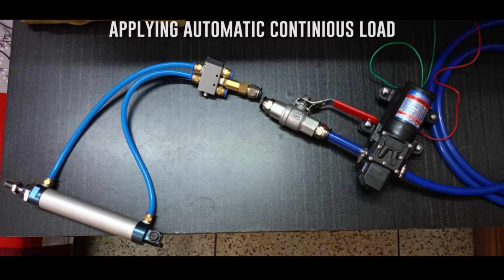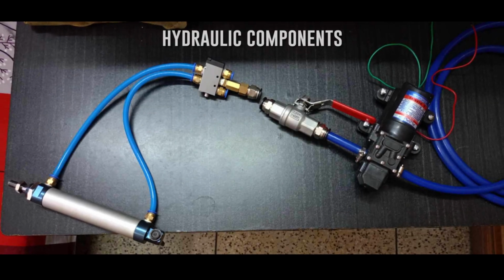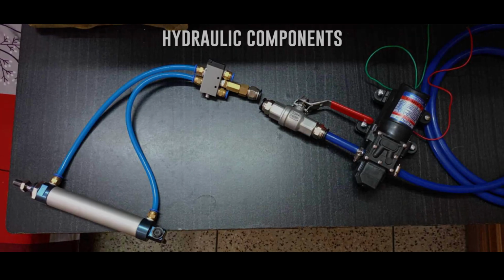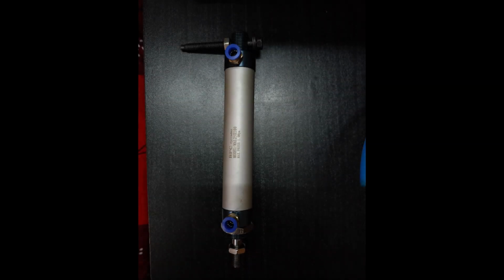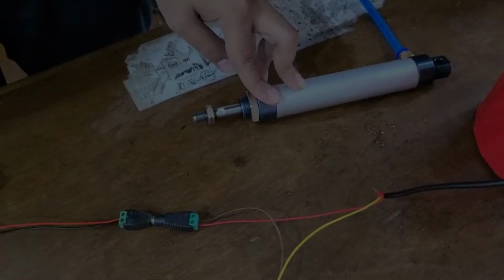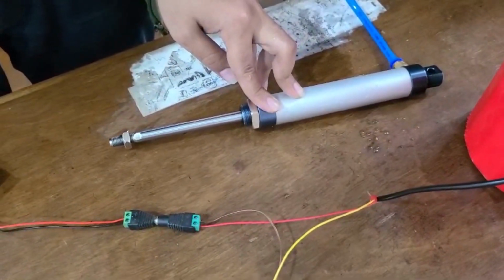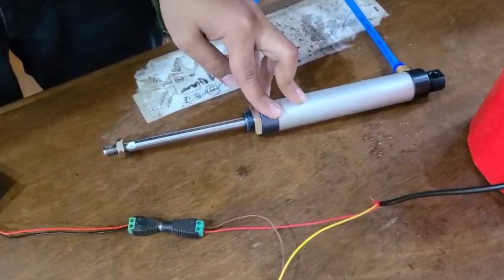For the first task, which is applying automatic continuous load, we used hydraulic components which are hydraulic cylinder, DC pump, ball valve, 5-2 directional control valve. This hydraulic cylinder was bought from Nawabpur. This is a double-acting hydraulic cylinder, which means that it can be both extended and retracted by fluid flow. It can withstand maximum of 1 megapascal pressure, which is more than we required.